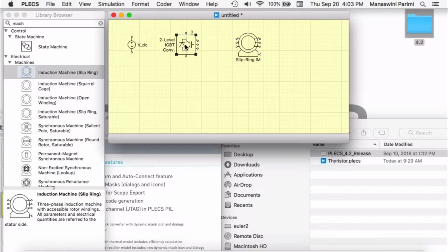So previously you really had to connect all the components individually, and in some cases multiple connections per component. Now you can simply click on a component and preview suitable connections by pressing the Alt or Option key on your keyboard, while the mouse is hovering over a compatible component.